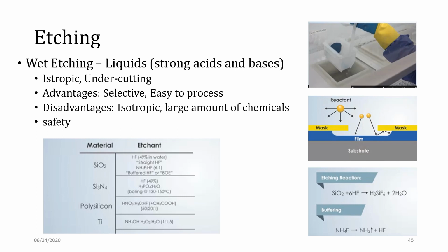And there are advantages and disadvantages. You deal directly with these chemicals, and these chemicals in wet etching can be strong acids and bases, which is a disadvantage. The advantage is that it is very selective. It forms an isotropic etch, and what really happens in a wet etch, if you use hydrofluoric acid, is that suppose you have silicon dioxide to be removed, it forms this, and it is easily removed.